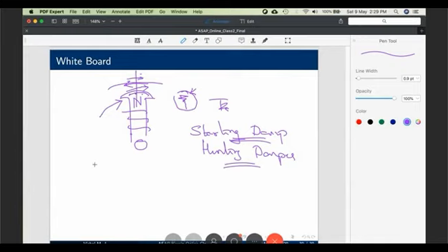You sense the speed, you extract the frequency component from that, and use that as the frequency to the stator. For example, consider a 50 hertz machine. 230 volt is the phase voltage. Now the rotor is rotating at some speed, correspondingly 20 hertz is the speed. Which means this will be your stator frequency as well. Now, what is the ratio K? It is 0.4, 20 by 50. Now, what should be the voltage you must apply? 0.4 into 230. How much will that be? 23 into 4.